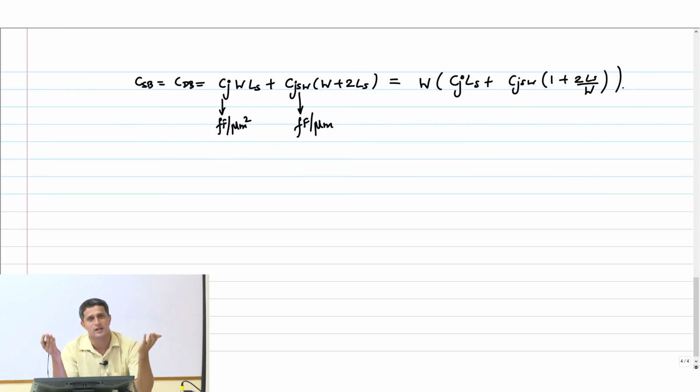What is known as parasitic delay of a transistor is to a first order independent of W. Parasitic delay is due to its own capacitances. Whatever I showed you now are the transistor's own capacitance. It's not any load capacitance. So they are called parasitic capacitances. So parasitic delay is to a first order independent of W, right? But of course, because I have a load guy coming in, it brings in some very interesting optimizations that I can do. We will look at all of that later on in this course.